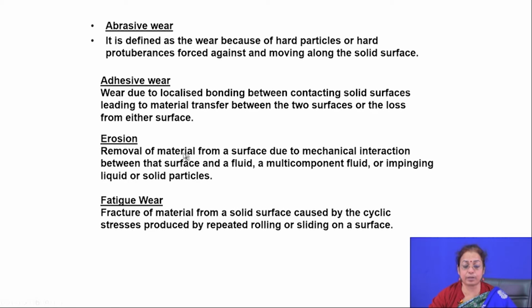Erosive wear is the removal of material from the surface due to mechanical interaction between the surface and the fluid, a multi-component fluid, or impinging liquid or solid particles. And fatigue wear is the fracture of materials from the solid surface caused by the cyclic stresses produced by repeated loading or sliding on the surface.